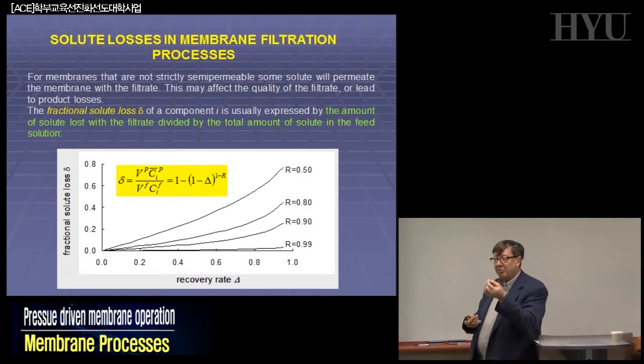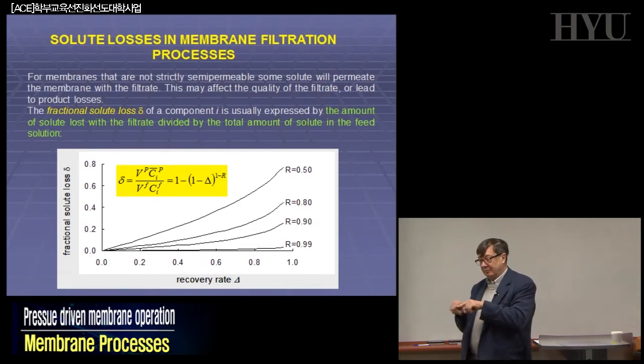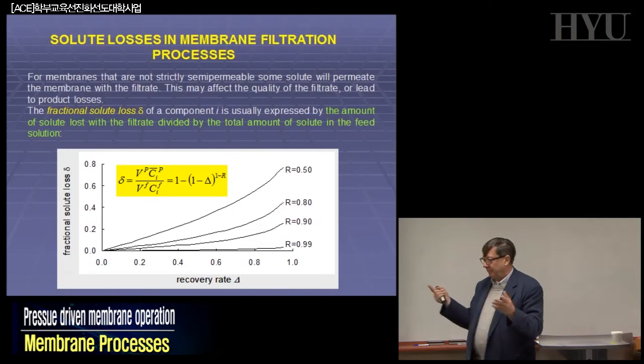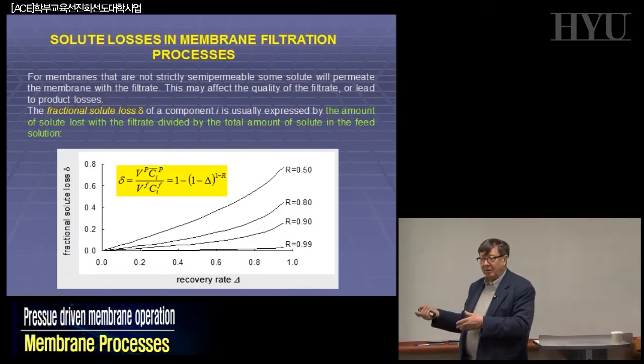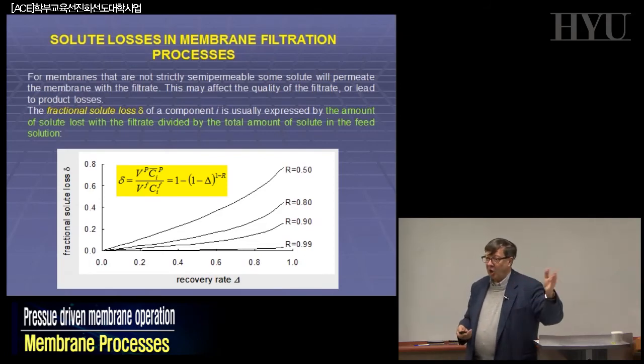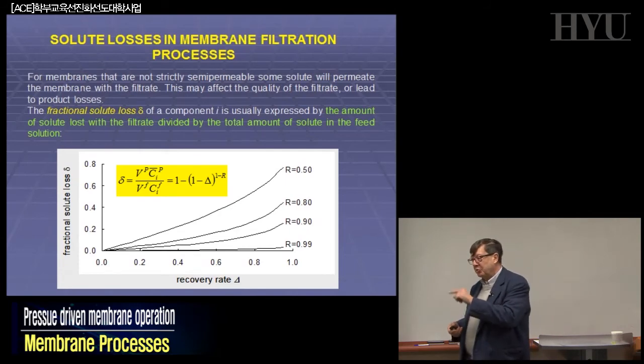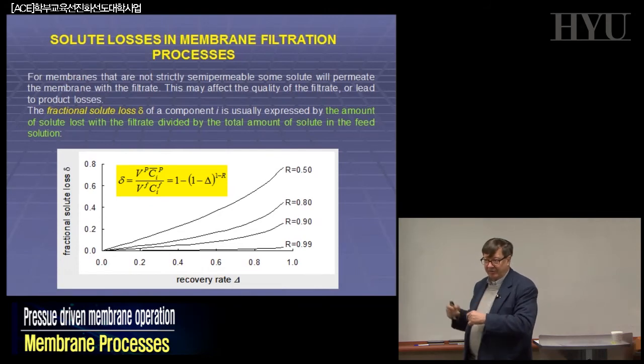The white spots are just molecules present in the water at very, very low dilution that were concentrated when the water was evaporating across the coatings. In a micro device, these molecules of salt were causing short circuits, just making electrical problems, and the parts were not working anymore. So these pieces were 40% lost due to white spots, which was due to the quality of water not being good enough for this kind of application.